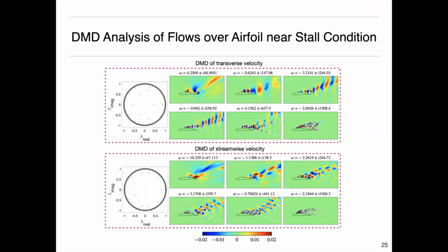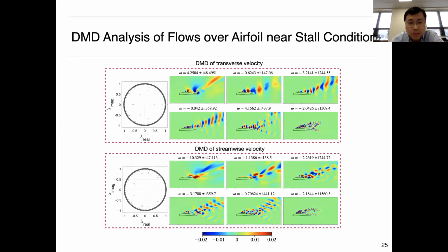If you were to plot the POD modes here, how would they look different? Oh, you mean the POD modes? Yeah. POD modes, generally, actually I didn't show it in this slide. In my previous paper published in Computers and Fluids, I show it. Generally, for the spatial modes, it looks similar. But if you check the details, there are some small differences. But the difference is for POD mode, you cannot find the dominant frequencies, but you can rank the energies for each mode.